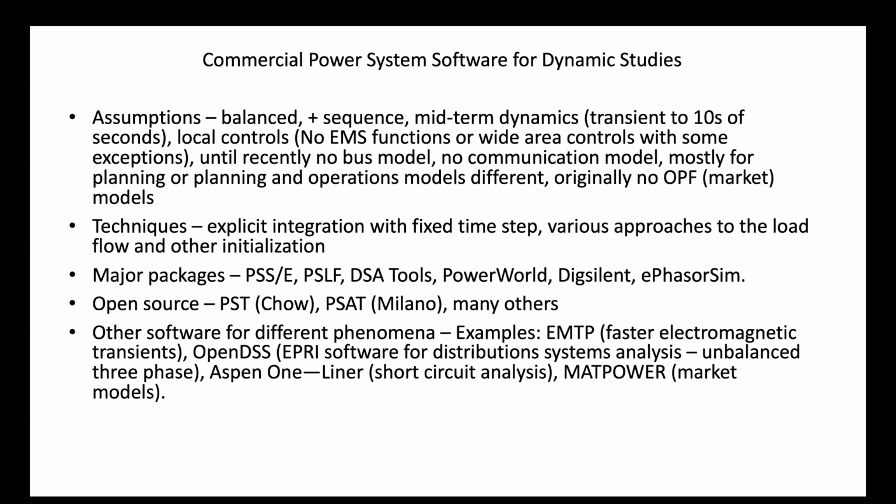Anyway, the bus breaker model is mostly for the operators. However, if you're trying to do other functions for controls, or you're looking at state estimation, you need that as well, because if some of those breakers are open, it changes the topology and so on. Okay, gotcha.